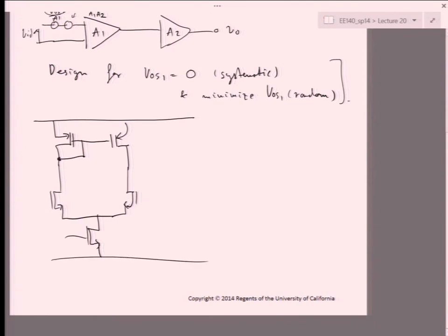If people remember the systematic gain error analysis with VTO, VTH, VOV going around KVL loops in current sources, well, the same thing happens here. Because after all, these are active loads. Okay. So we have a situation like this.